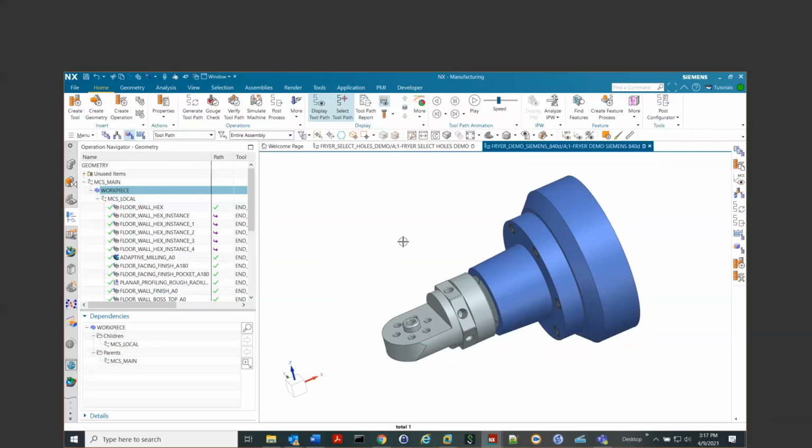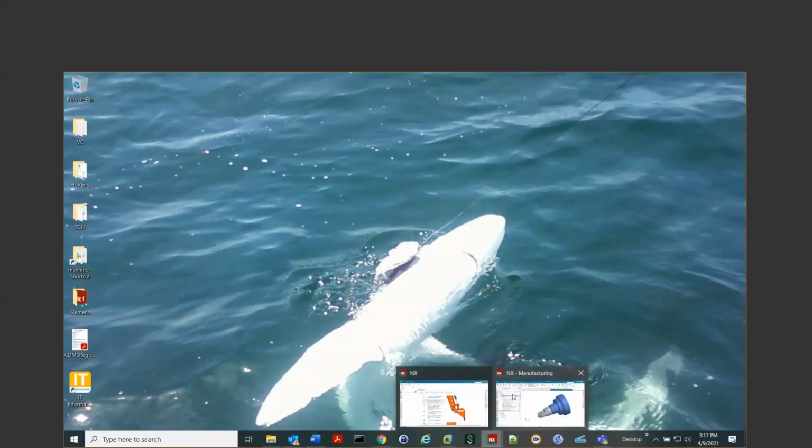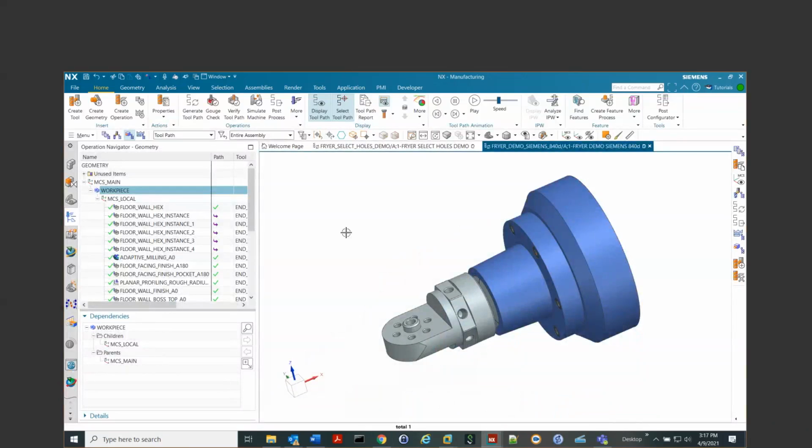Tom, is the simultaneous record able to be set so the spindle maintains a vertical orientation? Good question, Tom. When I have a machine space model in play, like you saw in Sinutrain, then it will, because it's driven by the kinematic of the machine. When we are running on the machine where either I'm not showing the machine space model or it's not available, like you saw on my machine here, then no, it's always going to be rolling the tool around the part. It's just the default method we chose when it's a milling machine.